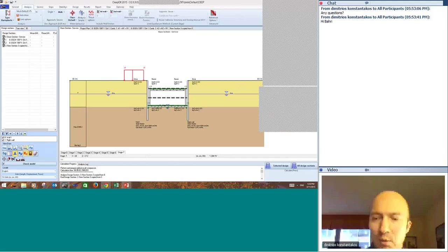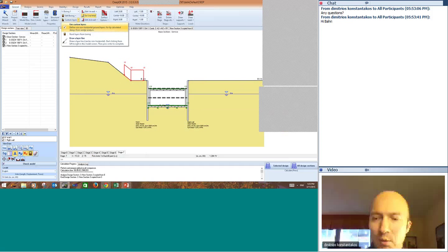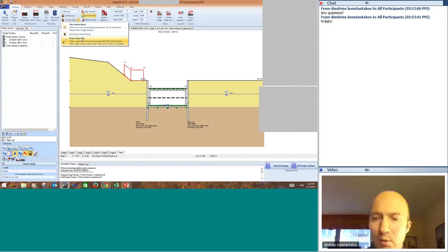So in fact, let's actually do this. You can backfill and create an arbitrary excavation like this, a surface like that. We can even go in the analysis and use custom layers, reset the layers from boring, and you can actually draw in. You don't have to have a horizontal ground layer.